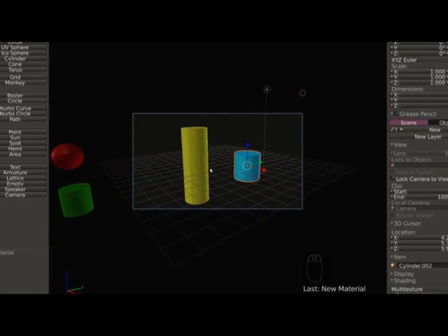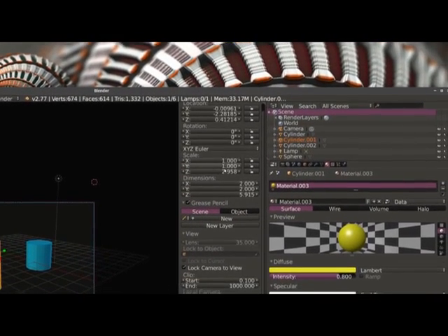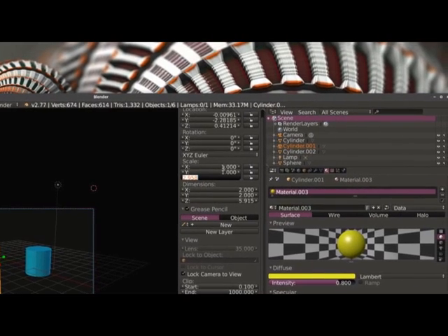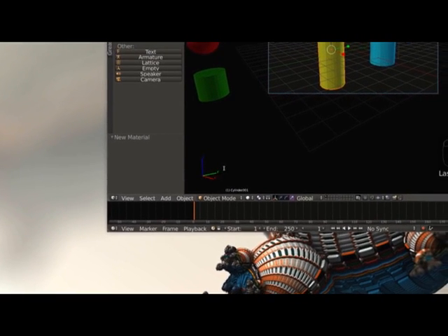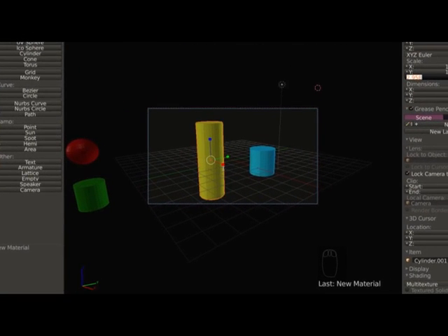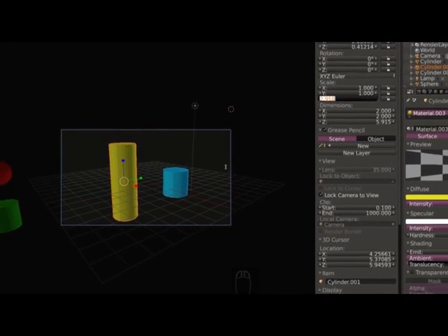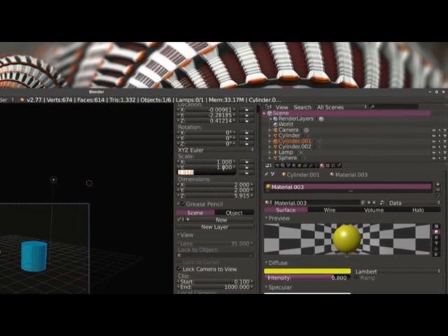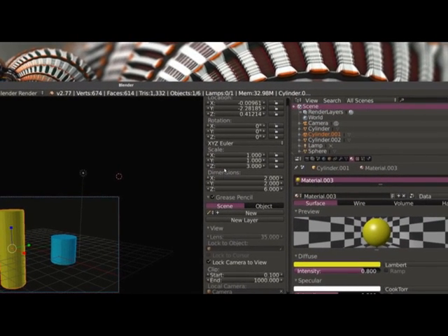I'd like to scale this cylinder similar to this one. So on this cylinder, you can see what I did is I put in a scale of 1, 1, and 3 just to make this easy. I'm going to change this number. So this is the scale, original dimension in the x-axis. Right. So if you look down here, x-axis is the red axis, y-axis is the green axis, z-axis is the blue axis. So this means that the x-axis, that's the radius of the cylinder in this direction, and the y-axis, the radius of the cylinder in that direction, have both been unmodified. They're both 1. X-axis scale is 1, that means its original size. Y-axis, it's 1. And then in the z-axis, it's roughly 3. So I'm actually going to change that to exactly 3. So it is 3 times the length of the original cylinder.